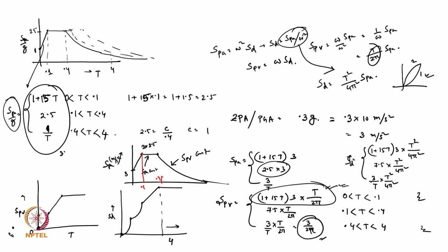But we also mention from that aspect that, okay, tall buildings, let's say a building having a 60-storied height. From the thumb rule, its time period will become 5 to 6 seconds. Generally that formula gives the higher side of the time period, so it will generally be lesser.